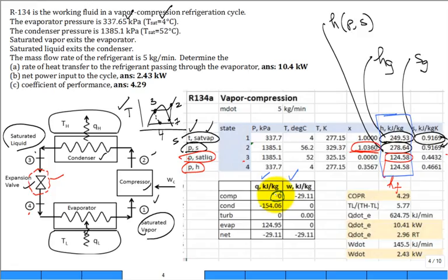Anyway, they're not insulated. If there's a little heat transfer, it only helps the system. But the standard assumption is 0. Same with the condenser. There's no work, absolutely no work. But there's no pressure drop in our analysis either. A real condenser will have a pressure drop. Likewise for the turbine. Now, I put minus signs because it's not heat transfer into the condenser, but out of the condenser. So when I do the sum of the Q's, the net Q is out of the system toward the hot. And the net work is not out of the system, but into the system.